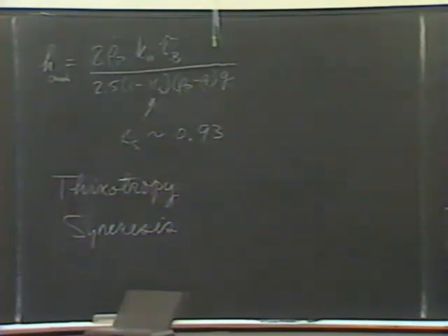These are structural changes in the material, but the most important one for our concern is thixotropy, because since the mud is just deposited, you don't see any evidence of syneresis. If it collapses a little bit, it just collapses. But the thixotropy is quite apparent.